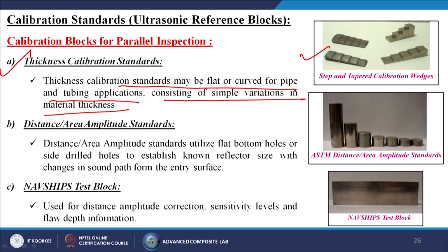So, simply we have a known time for that particular material. When you are using that probe, after a certain time we need to recalibrate it or check whether it is giving the exact result or not. That is why, after a certain time, at regular intervals, we need calibration testing.